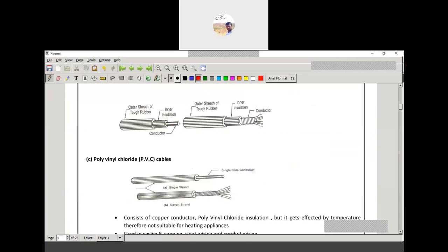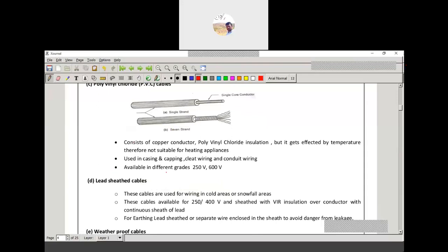Here are the advantages of the single core cable. It is very simple in construction. Electrostatic stresses developed are very small. Whatever the current around it, if any conductors are there, only a small amount of current flows, and due to the electrical stress the leakage current is also very small. It also offers a large conductor cross section, since only the conductor cross section is there.